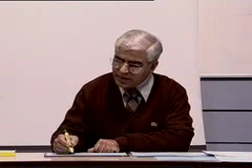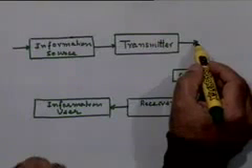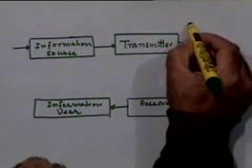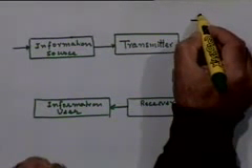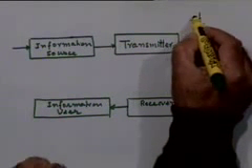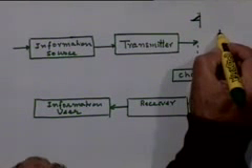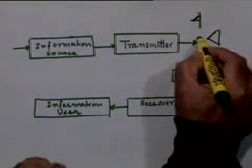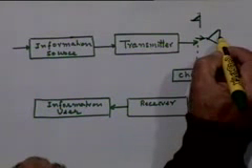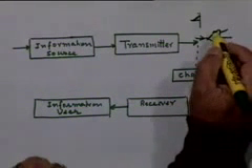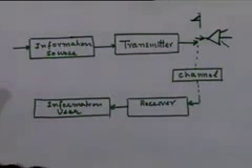the transmitter will have to radiate information into free space, right? Which essentially means it will have to have as a built-in mechanism an antenna here, which schematically is denoted by this notation. This is the notation for an antenna. So this is a signal coming in and it radiates, right? This triangle is usually used to denote an antenna in a communication system block diagram. But physically an antenna could be one of many types depending on what frequency range you are working with.